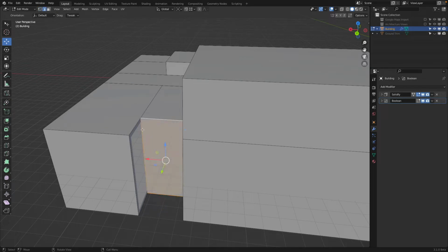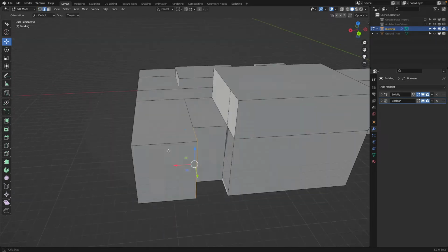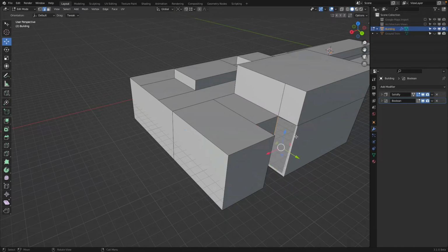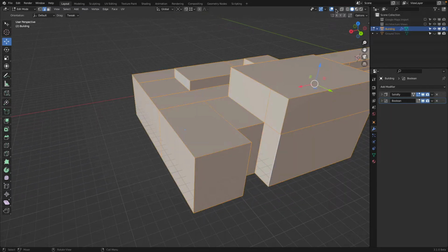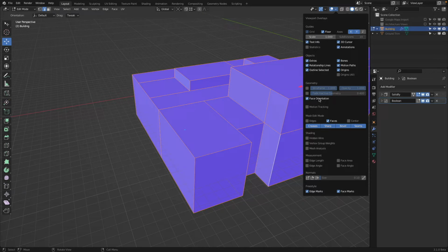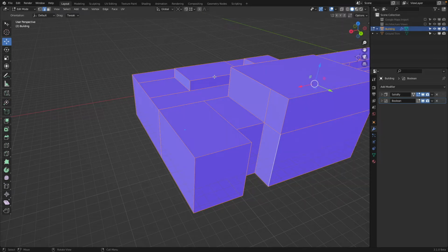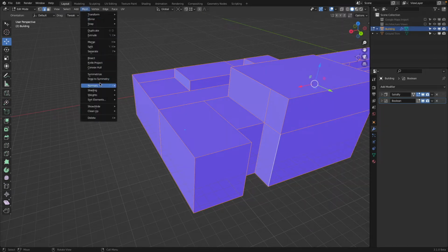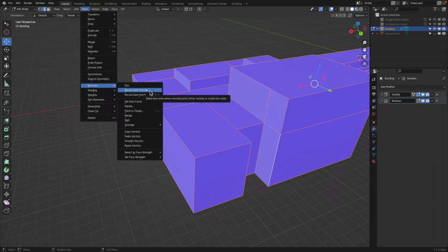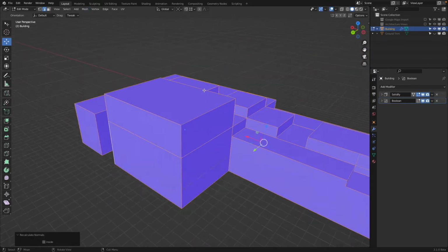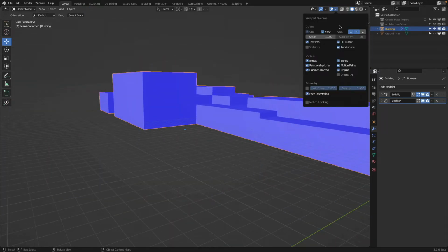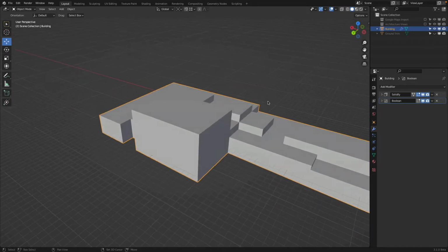Second way is these 2 points I delete. Edge select, F, select all these edges, and you see I'm just rebuilding them. A, select everything. Let's see, face orientation is good. Shall one be red? Then we simply go to here and say calculate outside. Done. Okay, very good. So that wasn't too complicated.